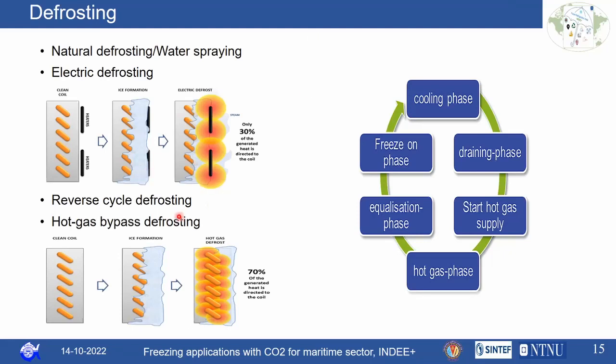And there is another method that is called reverse cycle defrosting. This reverse cycle defrosting is normally carried out in the case of a heat pump, where your evaporator will be frosted. So you can actually reverse the whole cycle to defrost the system, which cannot be adopted here. So in our case, we'll be going for a hot gas bypass defrosting, where you will take